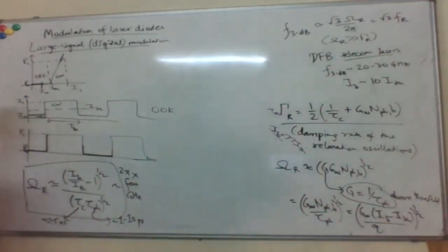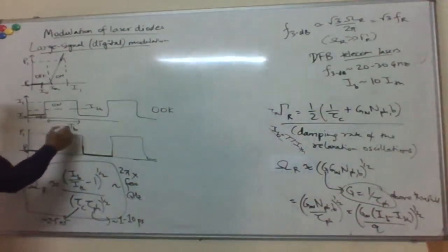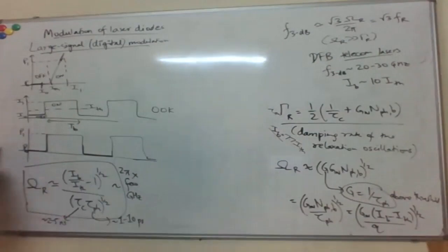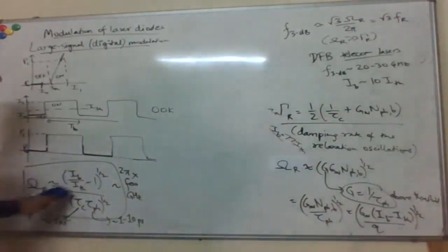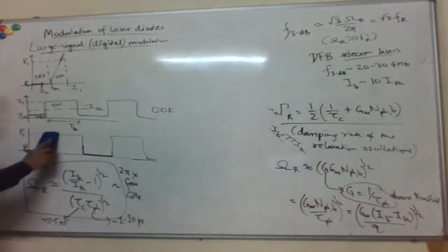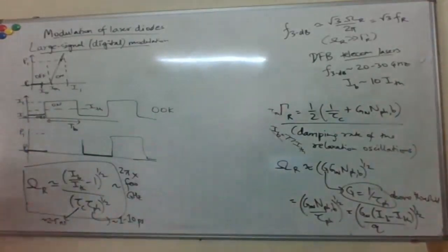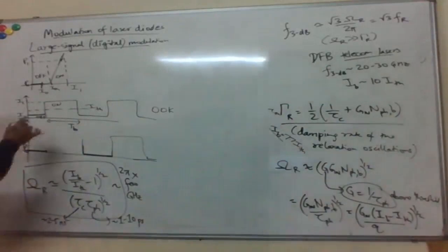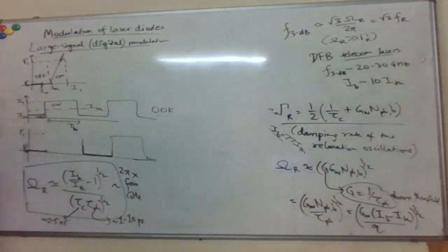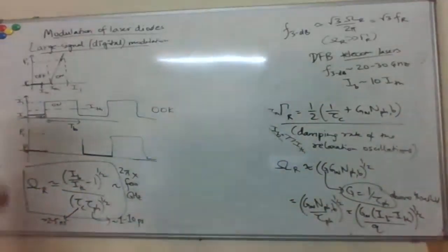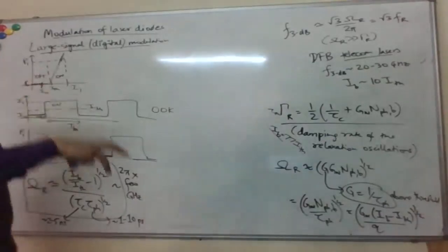will start to matter. So if I'm looking at very high data rates, now this doesn't look vertical on this time scale. What you actually see is a manifestation of this relaxation oscillation that I was talking about. Imagine what is happening in the device. As soon as you increase this current, you're suddenly injecting a lot of carriers into your device.